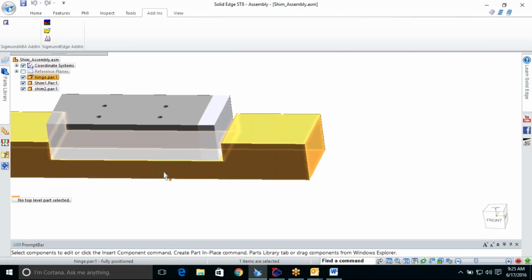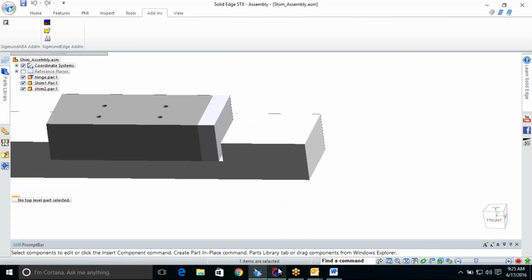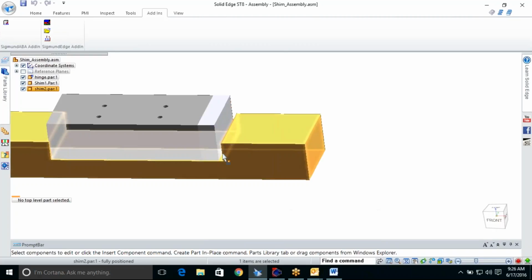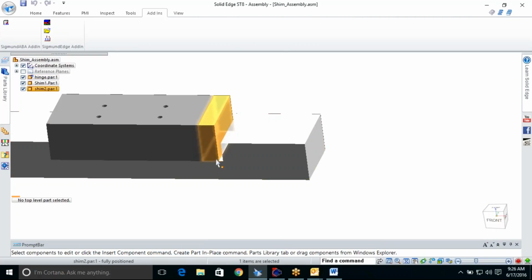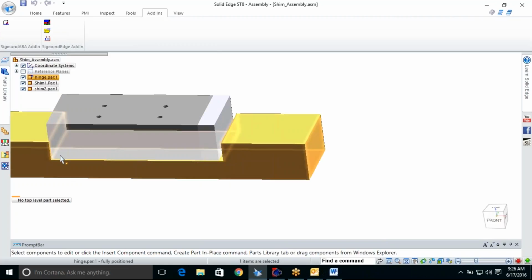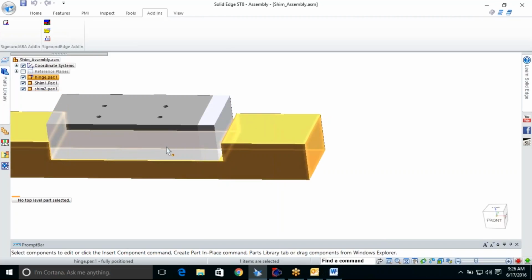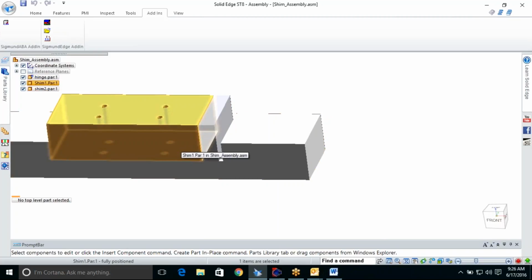And based on the way the components are dimensioned and assembled, I have from this surface to this surface. So it is essentially the width of this minus this width and this width. So those are the three tolerances that would have an impact on this particular objective.